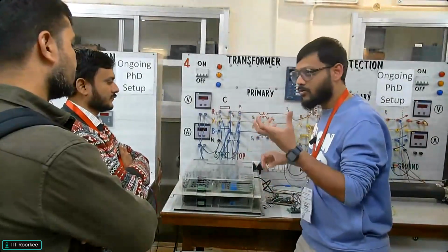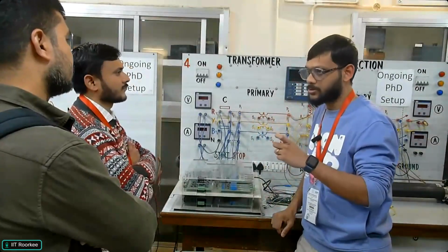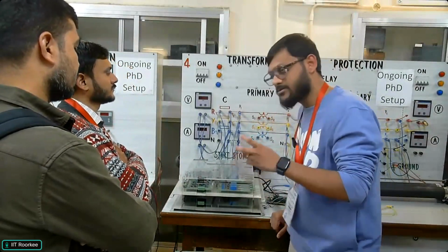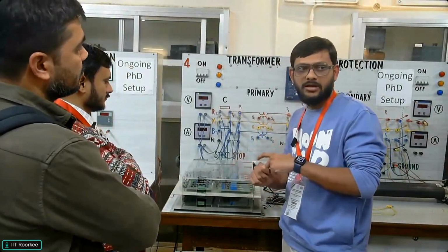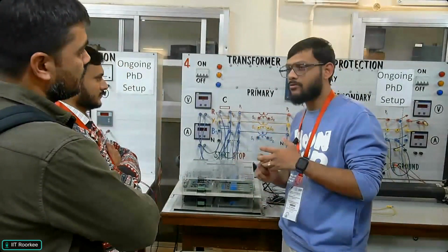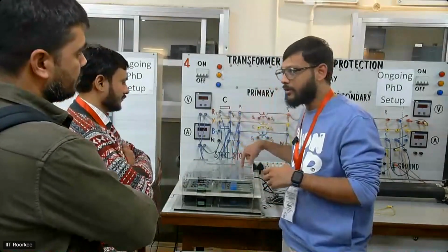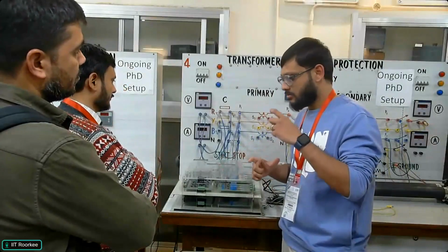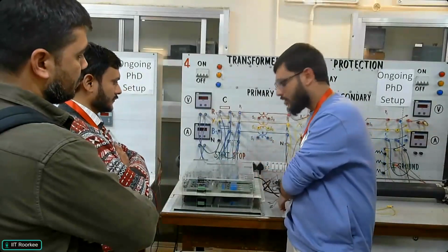But if you have a DSP, you cannot connect 1 ampere. You need to convert that into appropriate voltage levels. So what we have done is use a DSP controller based on TI, and we are creating our protection algorithms. TI has a limit of 0 to 3 volts only. So you cannot give negative, and you cannot give above 3 volts. So these circuits convert whatever current we give into the 0 to 3 volt limits. Now this 0 to 3 volts will be given to the ADCs of the Texas Instruments board.